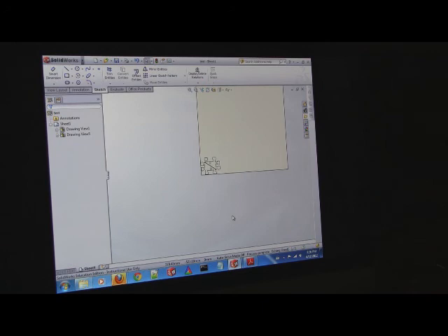When should they change the colors of the holes in the appearance? I only do that if there's something special about it. My convention is blue for a special type of fit, like a press fit or a slip fit, and red for tapped. That way, if the hole is the same color as the rest of the part, I know not to worry about it. I should have put that in the homework. Red for tapped, blue for press fit or slip fit.